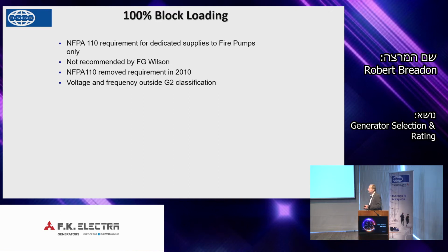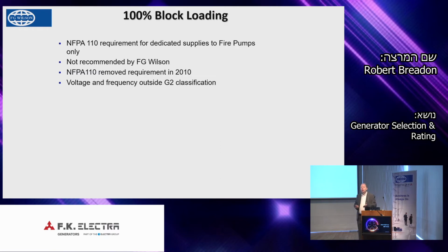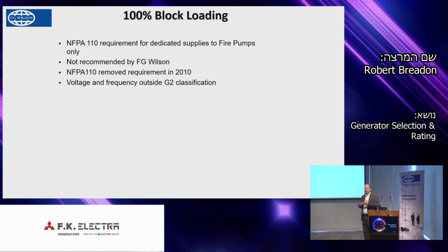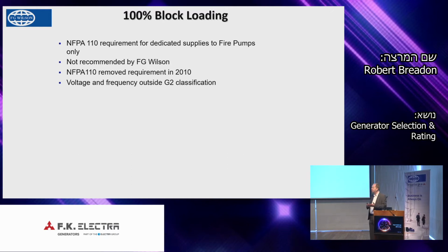With the lobbying of all the engine manufacturers, NFPA removed the requirement for this 100% load step about 10 years ago. They saw it as not a good thing to do to your engine, a brand new engine, especially the large turbocharged engines. They were lobbied by all the engine manufacturers to take this out, because initially this was designed for a dedicated genset against a dedicated pump for a life safety environment.